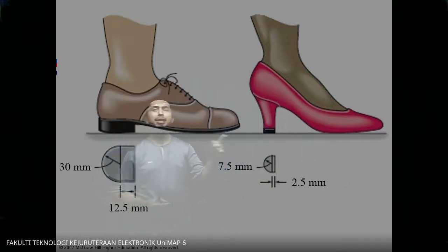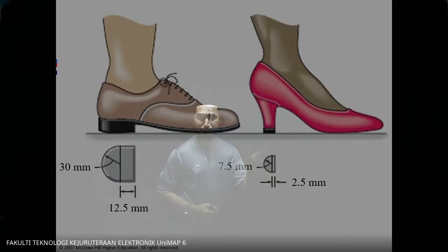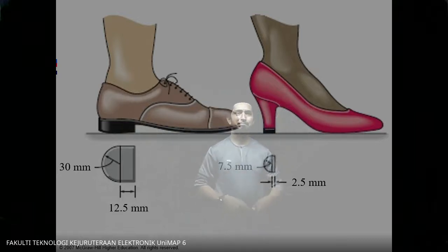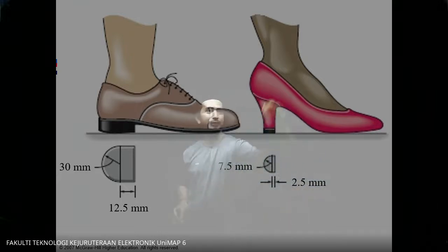Convert first, millimeter into meters, then find the area of both conditions, then force divided by area. Boleh tak kita try? 2-3 minit je. Without looking to the notes, try on your own. Salah tak apa.